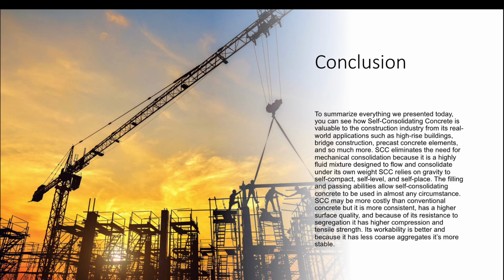Self-consolidating concrete may be more costly than conventional concrete, but it is more consistent, has a higher surface quality, and because of its resistance to segregation, it has a higher compression and tensile strength. Its workability is better, and because it has less coarse aggregate, it's more stable than conventional concrete.